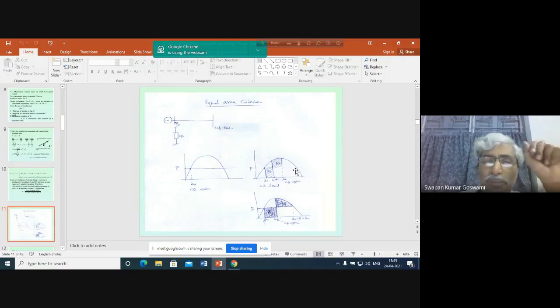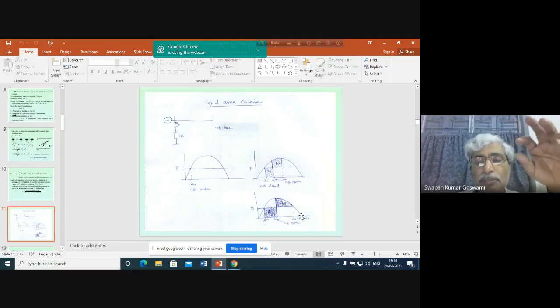Why are we talking about pi minus delta 0? Because unless the synchronous speed is restored before this point is arrived at, or at this point, the system or generator will not be able to maintain synchronism, will not be able to regain synchronous speed. Why? To understand that, we have considered this figure. You see here, the same power angle curve we have drawn again.